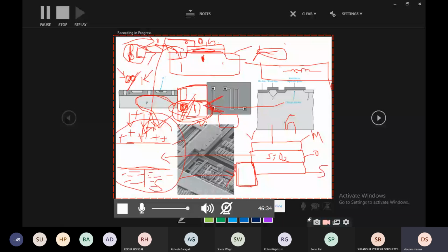But recent developments in the RF domain have created the need, and we have to do it, right? How can that inductor be fabricated? Basically, what is an inductor? It is nothing but spiral wound, right? Any wire, if you wind it spirally, then it will behave like an inductor. So it can be fabricated using spiral wound thin metal films on that IC. Spiral wound thin metal films, right? Metal films means what? It is basically like wires only, right? Thin wires.